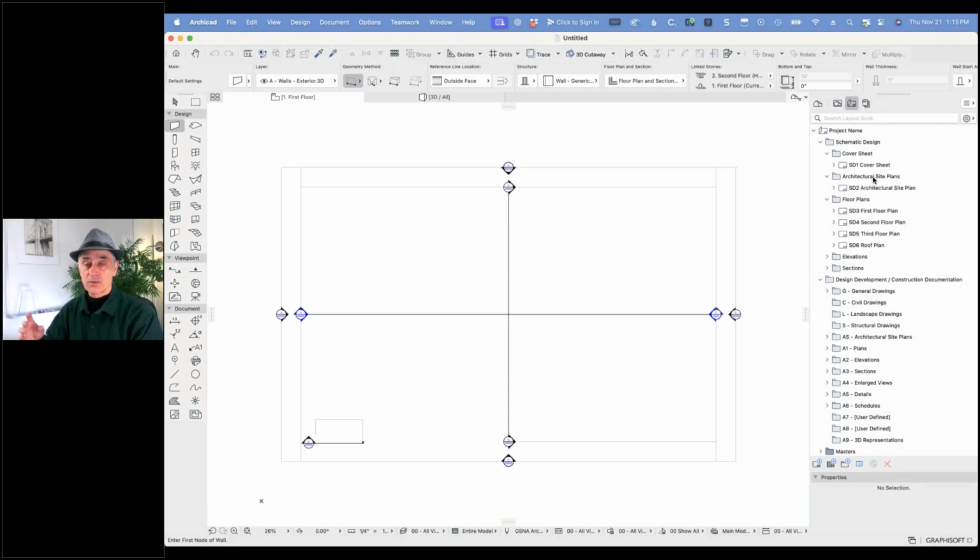Okay, so far just talked about what's drawn there, not much. What's put into the navigator, quite a bit. All these views define, well, what's the difference between a floor plan and a ceiling plan? Well, different layers. You show the ceiling layers and maybe the lighting and things like that on a ceiling plan, and you turn off some of the lower details of, maybe lower cabinets or other things. Certainly you turn off furniture. What's the difference between a floor plan and an electrical plan? Well, you turn on layers for electrical stuff, site plan, etc. So all of that's sort of carefully defined.